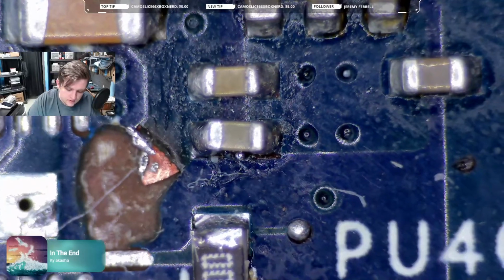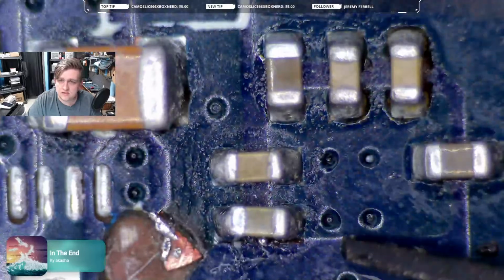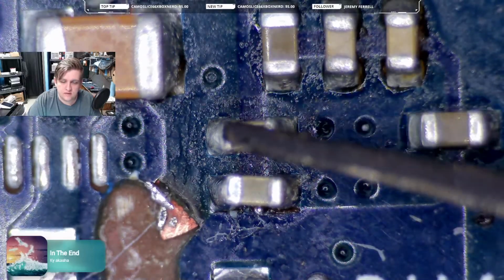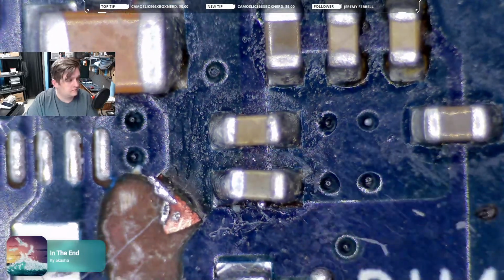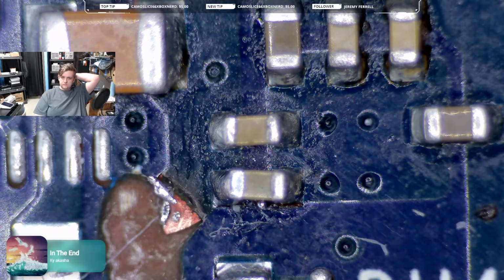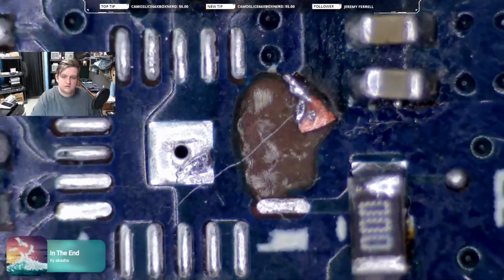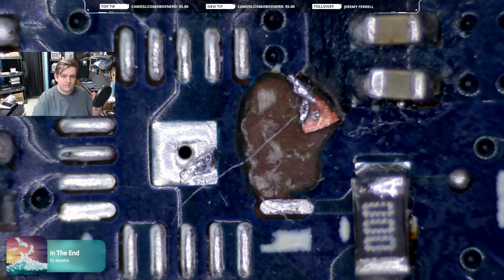But we do have these caps here that the spec sheet said to use to decouple these pins from ground. Could these caps be bad? Maybe. Because they're supposed to stop voltages from, I guess, leaking or shorting the chip to ground. But I really do suspect that this is from a faulty power supply, because these are inline chips, and those were inline traces to that chip, and the chip was overloaded by bad current.